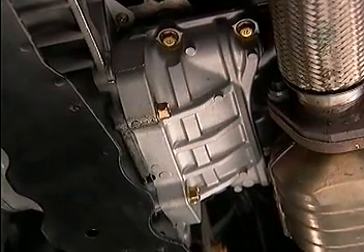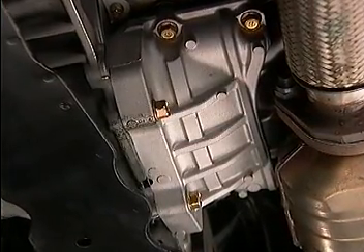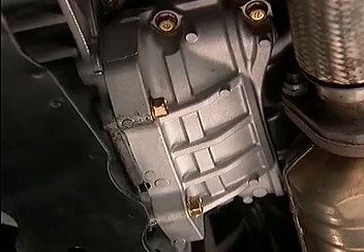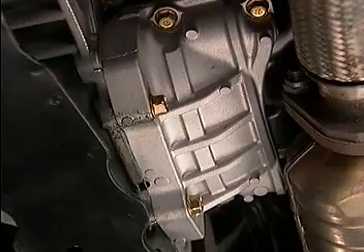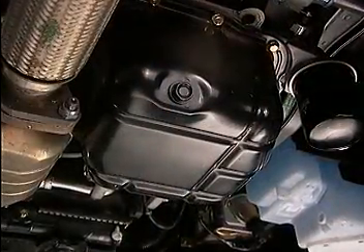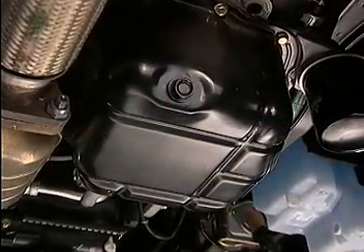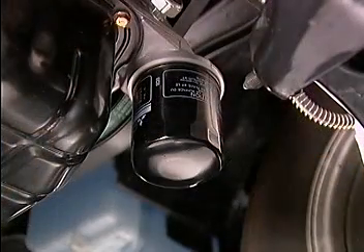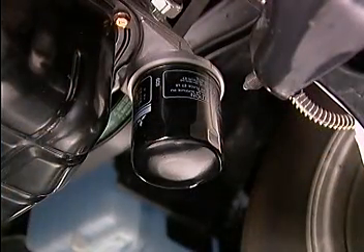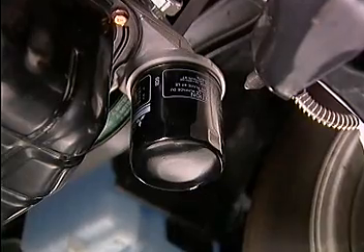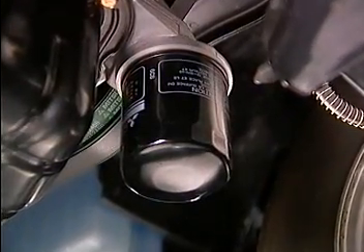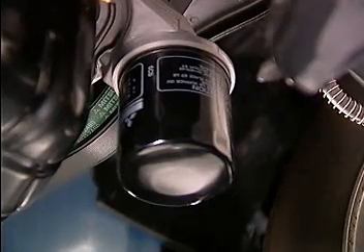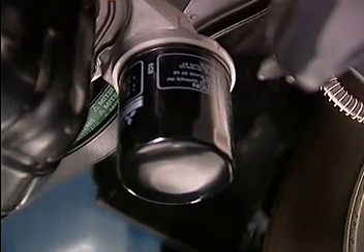Technical improvements on the 1.8-liter engine include an aluminum brace to increase the rigidity between the engine and the transaxle. This brace helps to reduce powertrain noise. The oil pan is now made of low-noise steel plate for a quieter engine, and the engine oil filter has been relocated from under the exhaust manifold to the front of the engine for easy access. Remember, do not install an automatic transaxle filter here by mistake.